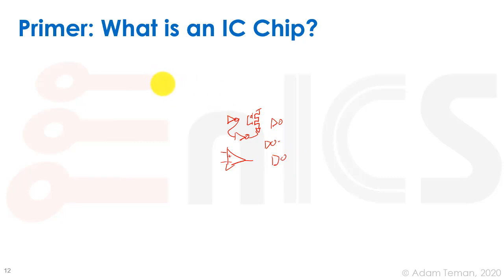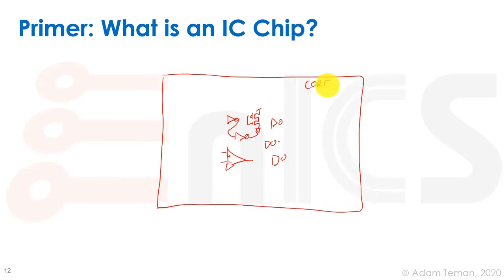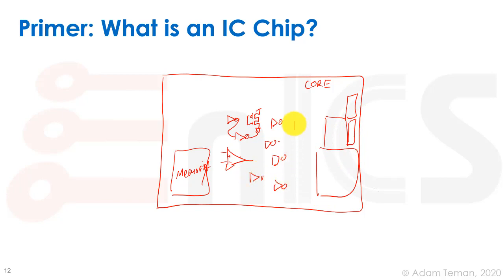So when we take our chip, we have this area that we usually call the core area, where all of our logic is scattered around. So that's going to be a whole bunch of these, and I'm talking about a lot of these transistors that make up these gates, and some of these analog blocks, and a lot of memories. Usually we'll see the memories as a bigger kind of a block, like in all kinds of places around the chip. Okay, but everything else is going to be these different gates and transistors, and maybe again here's some sort of analog block, maybe like a PLL or an ADC, or different types of blocks like that will be around.